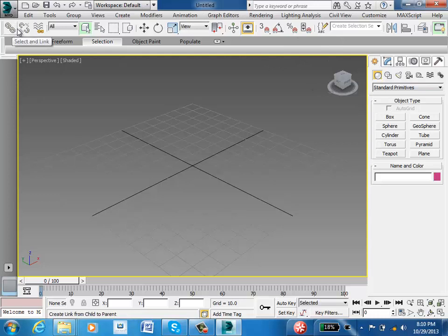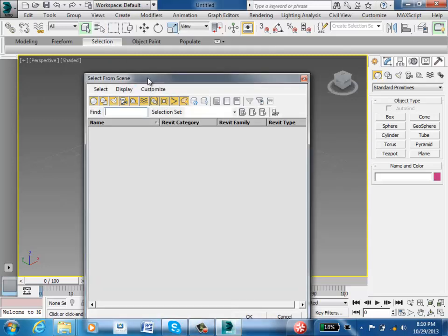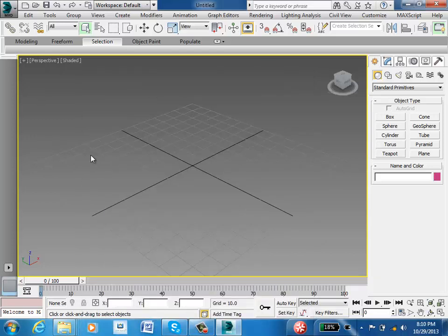So here you can select and link different objects together. There's the selection tool right here, which basically, as I click on objects in the model, will select those objects. There's also select by name. Some of your models can get really complex and you have a large number of objects. So if you just want to select a light or something like that, you can limit, and I'll show you this later, what shows up in select by name, and that can be a very useful way of selecting objects. You can make rectangular selections, and then there's move and rotate and scale. This moves, rotates, and scales different geometries in the model.